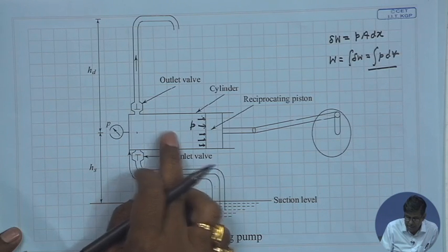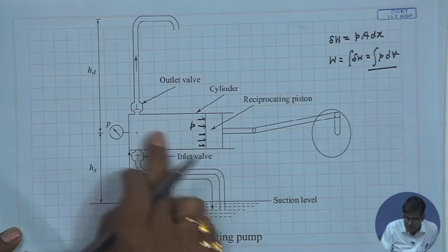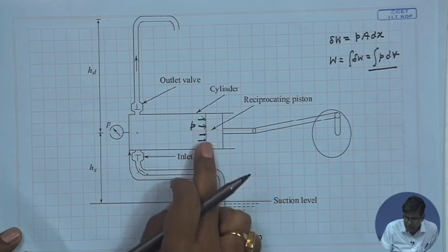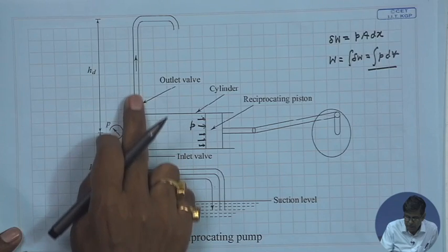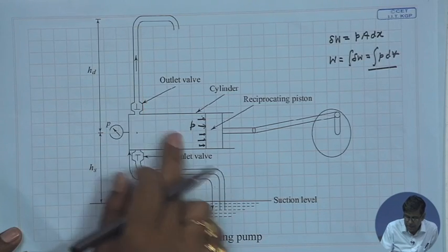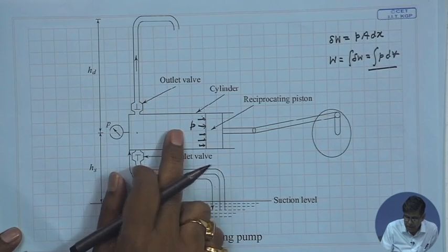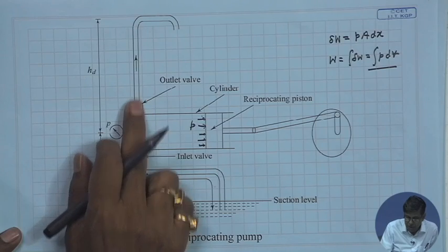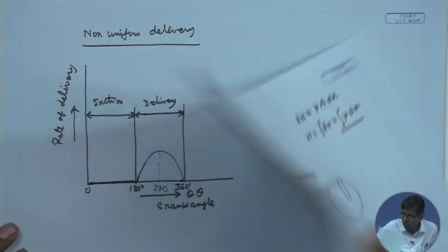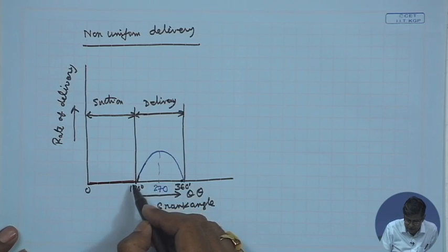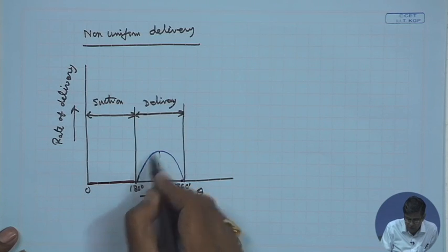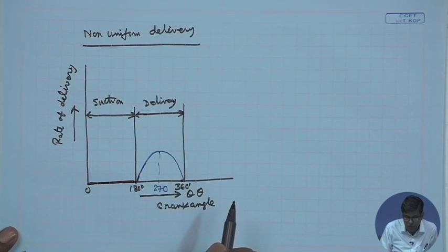So, this results in a variation in the flow velocity in line with the velocity of the piston, and similarly the pipe velocity only varies in magnitude by the ratio of the areas. So, therefore, the discharge, which is proportional to the flow velocity, also varies in the same fashion as a sine curve. So, you see we get a non-uniform distribution.